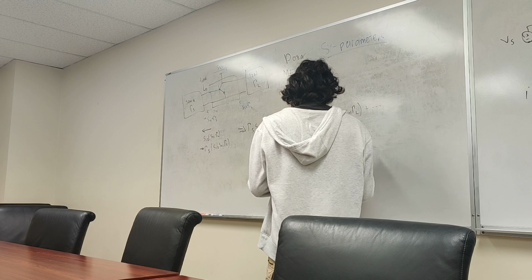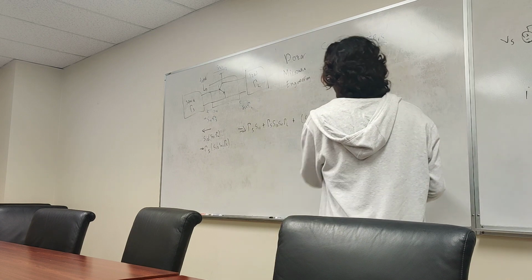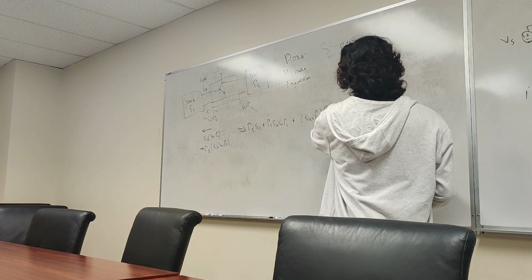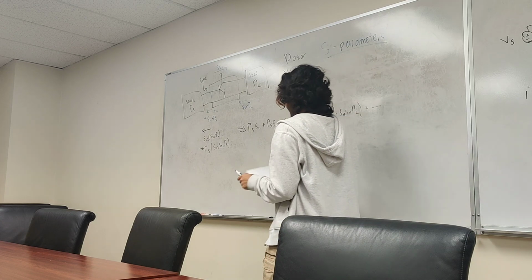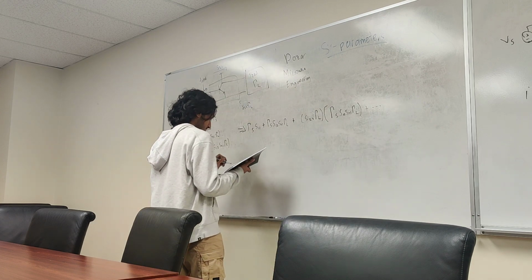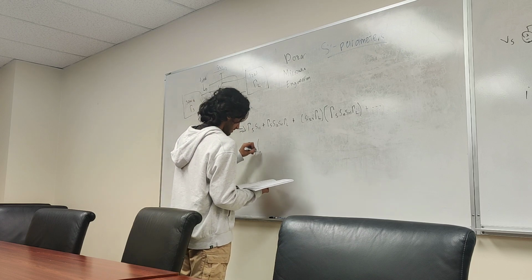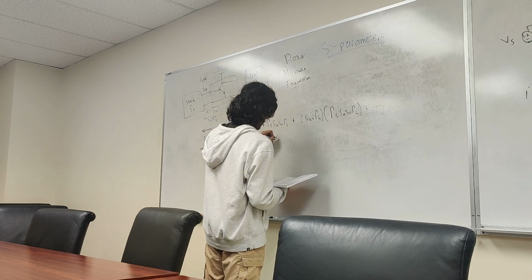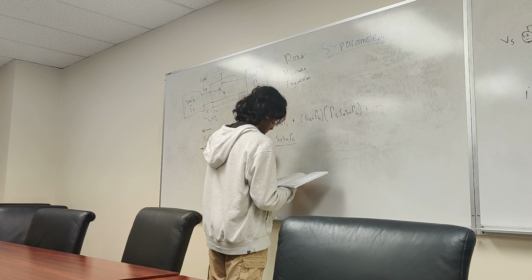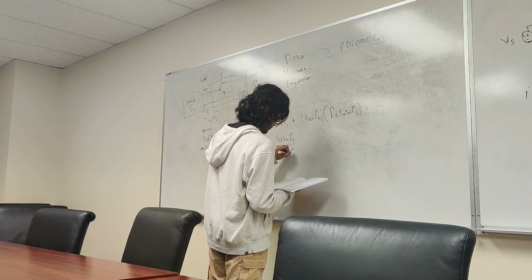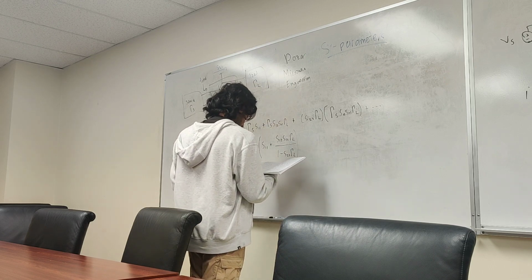So this goes on infinitely. If we want, we could factor out a gamma S from everything. And if we do a Taylor expansion of this whole thing, we can see that this infinite sum is equivalent to gamma S times S11 plus S12, S21, gamma L over 1 minus S22, gamma L. Okay.